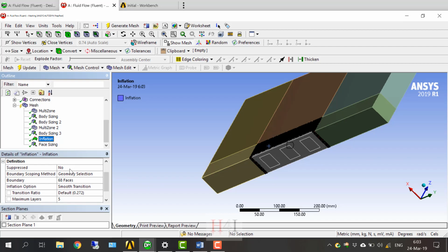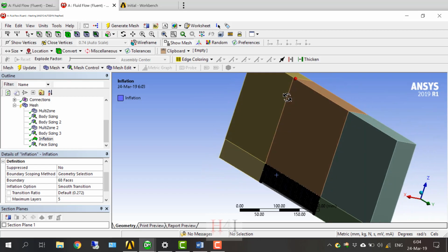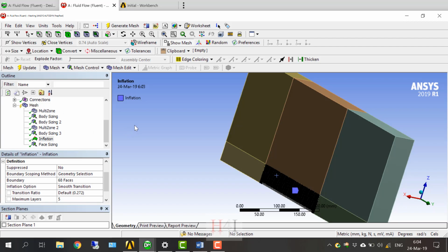So I have a question regarding the mesh quality. Professor Kawara suggested that deformation in meshing is not a sign of good mesh, but you suggest that this one is a good mesh. This kind of deformation is not bad. Bad deformation is something very skewed, with very small or very large angles, but that is not the case here. If it occurs in one cell or two cells, this is not a problem.